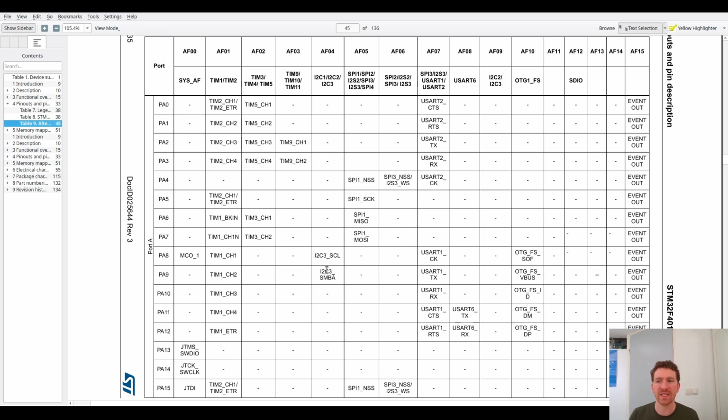The only thing we really care about in this instance is finding a bunch of pins that relate to a single timer that give us access to a couple of channels, and then that will give us the freedom to choose whatever other timer that we have in order to actually generate the interrupt. We need 2 timers, remember.